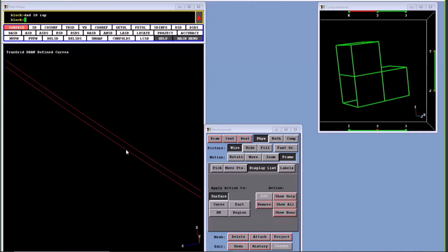A similar thing happens if you say, I want an edge of my mesh to be on the intersection of two surfaces, but the surfaces don't quite meet. The algorithm, with no special case, will extend the surfaces tangentially to find the intersection. Again, no special case is considered.